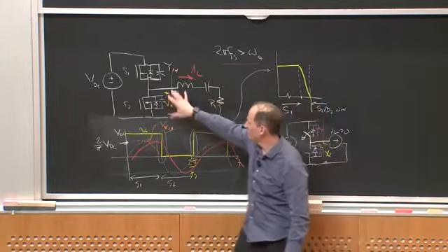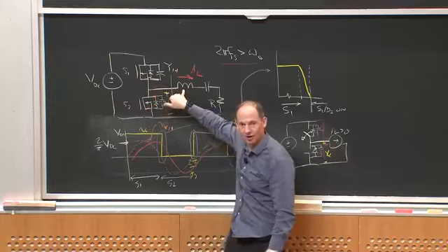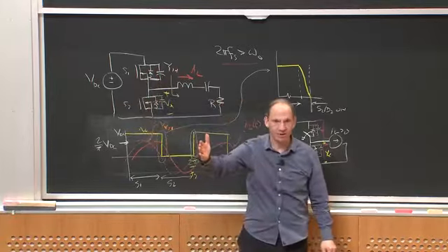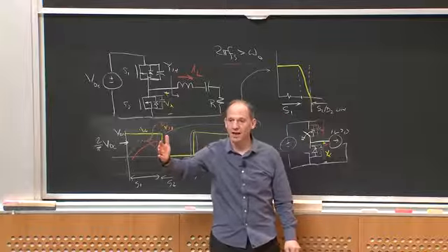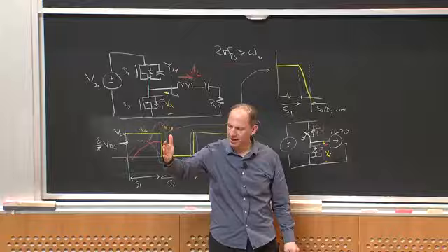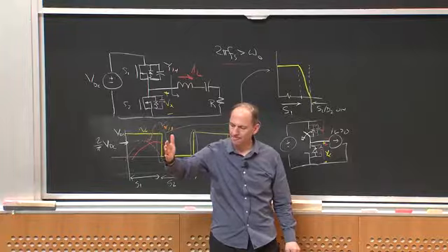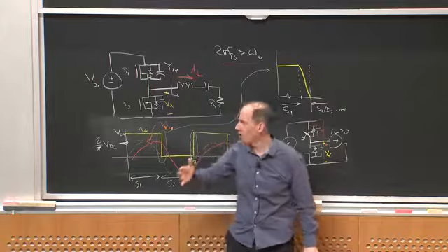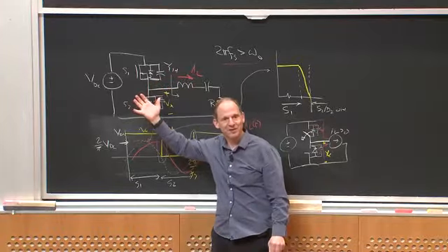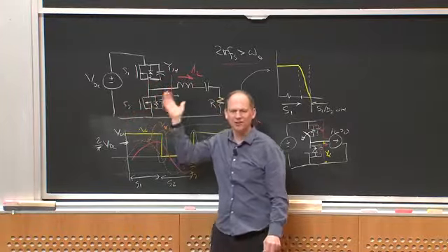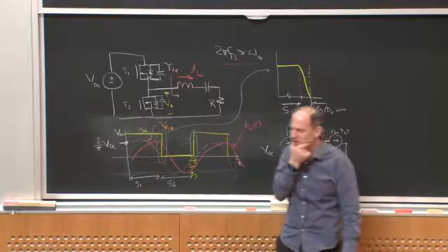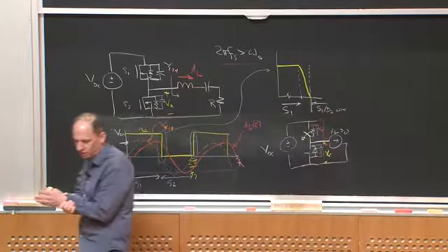But that also means that the device currents and the inductor current and the capacitor current also got lower. So this kind of characteristic has the nice habit that as I'm reducing power, all my currents in my devices and components go down. So I can keep efficiency high as my power is getting lower and lower. That's a nice characteristic of a series resonant converter.